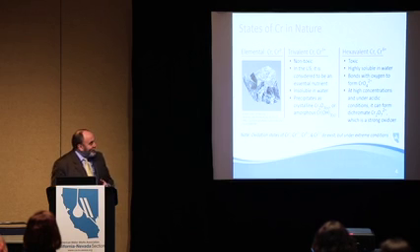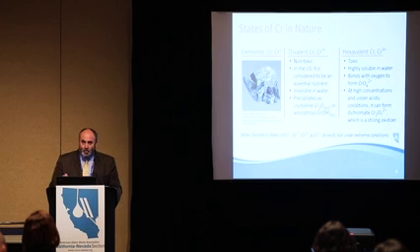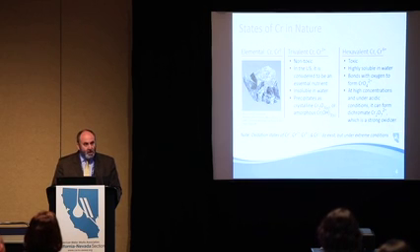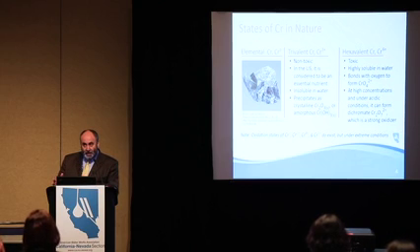It can precipitate as a crystalline structure, Cr2O3, which is a harder, solid precipitate. But in typical water applications, it precipitates more as a chromium hydroxide, very much like ferric hydroxide and aluminum hydroxide precipitate. So it's a solid product, but a very amorphous and light product. So Chrome 3 is insoluble and it precipitates very readily.